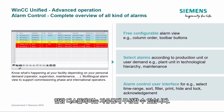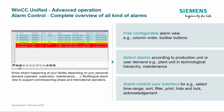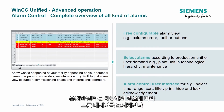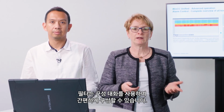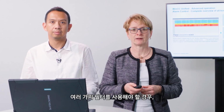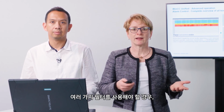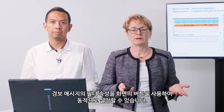The alarm display can be freely configured. This not only concerns the columns displayed and their sequence, but the toolbar as well. Using flexible filters, only those messages for an individual area, such as a machine, can be displayed as needed. The filter can easily be composed using a configuration dialog. If various different filters are required, the filter properties of the alarm message can be made dynamic using a button in the screen.